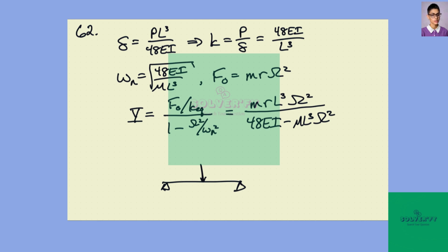And we're told that from just strength of materials, which you may or may not have had that class already, the deflection of a beam that's simply supported like this at its middle is the load, P, times the length of the beam between the supports cubed, divided by 48 times the Young's modulus times the area moment of the cross-section.